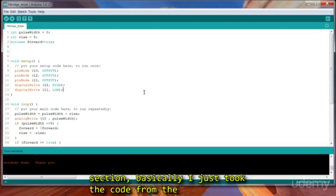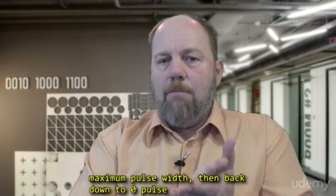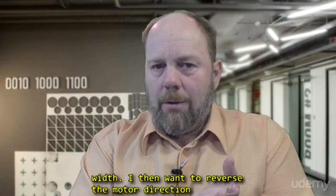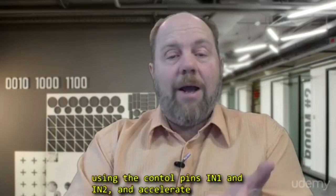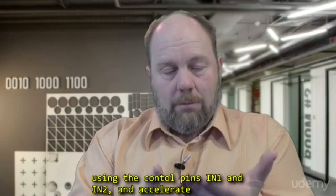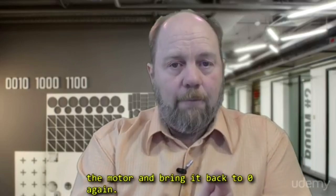Basically, I just took the code from the last lesson and hacked it to death. Now what I want to do is accelerate the motor to maximum pulse width, then back down to 0 pulse width. I then want to reverse the motor direction using control pins IN1 and IN2, accelerate the motor, and bring it back to 0 again.